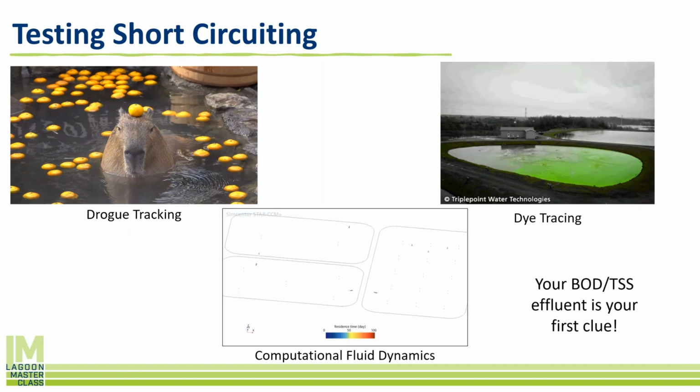So there's a few ways that you can test for short circuiting. I think the best and easiest is using dye tracing, although this does cost some money. And what you'll see here is we had a lagoon system. We wanted to do an evaluation. We put some dye in the influent structure, and you'll see it pop up right here first, and then go out the effluent pipe right here that you see.